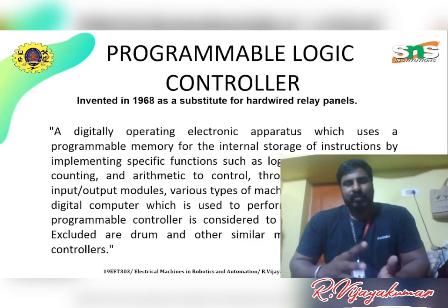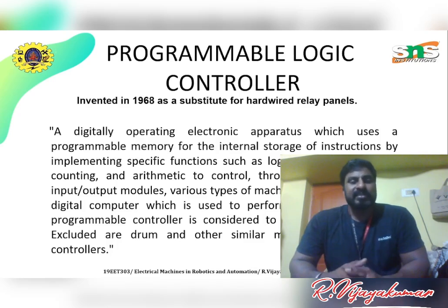So PLC, programmable logic controller, was invented in 1968 as a substitute for hardwired relay panels, a digitally operating electronic apparatus which uses a programmable memory for the internal storage of instructions by implementing specific functions such as logic sequencing, timing, counting, and arithmetic to control, through digital or analog input or output modules, various types of machines or processes. The digital computer which is used to perform the functions of a programmable controller is considered to be within this scope.